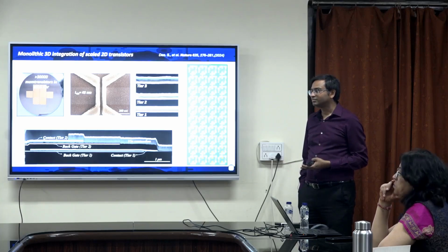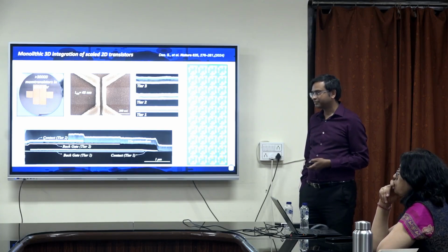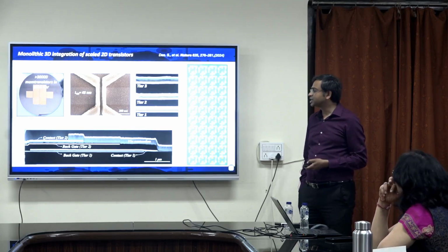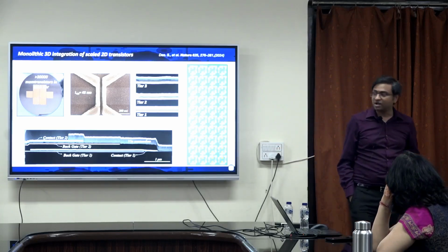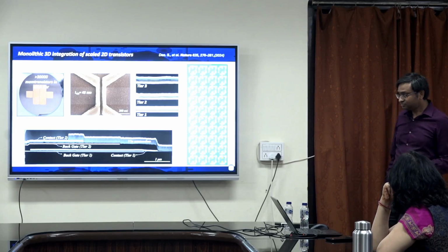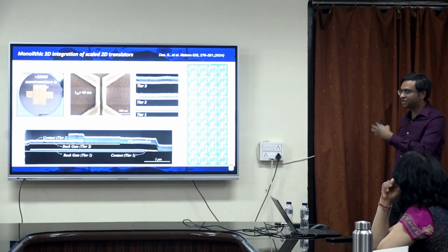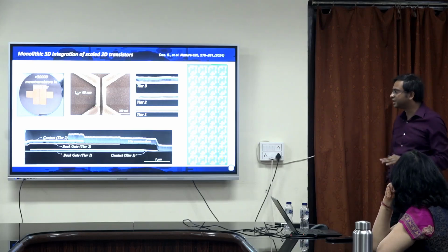More than 30,000 devices at this channel length is huge. That means you use, I think, E-beam lithography. Yes, E-beam lithography. The E-beam takes at least 8 hours to write the entire chip, 8 hours for one tier, and then another 8 hours for another tier. So there are a lot of lithography steps. I will come to that.